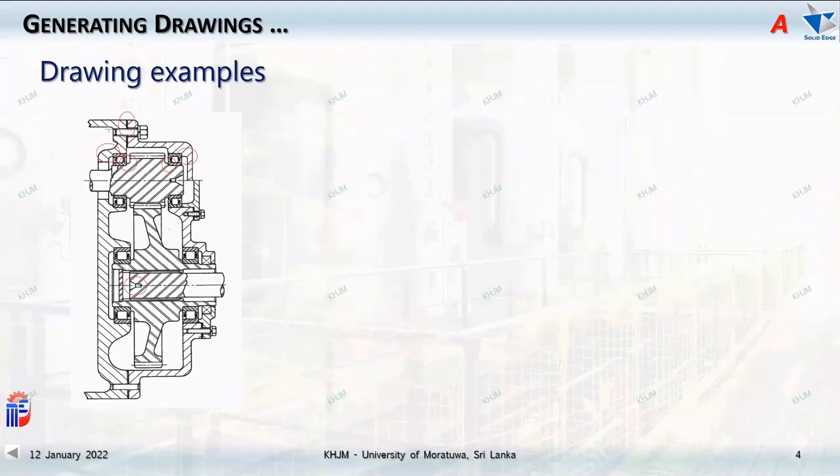You see, this particular end cap is going to contact one side, that is the housing, and the bearing outer ring. If you think of the dimensional tolerances, if this height is smaller than the width or thickness of the bearing, then maybe this side will be in contact first.